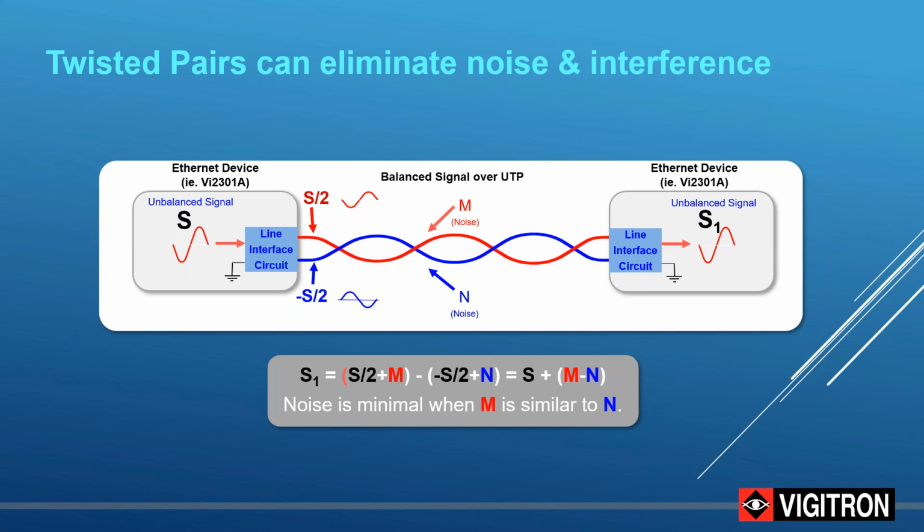Once again, what is the difference of CAT cabling or what we call flat cabling or untwisted cabling? Well, one of the reasons that CAT cabling was selected to be the standard for IP PoE transmission is because its twists result in a lot of noise canceling. And by noise canceling, we open up the channel for more signal. When noise is on the line, it takes the place of signal and reduces the amount of signal and therefore the amount of distance that the signal can be carried.